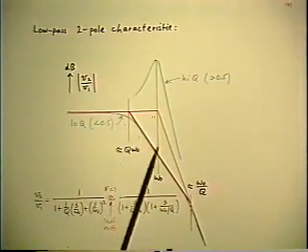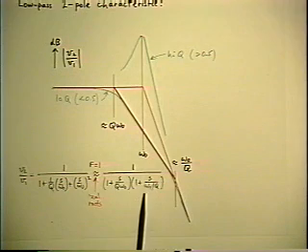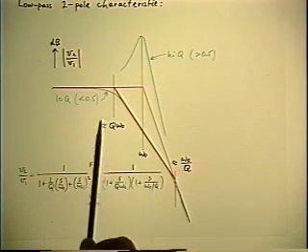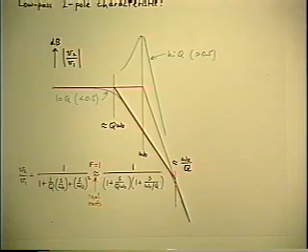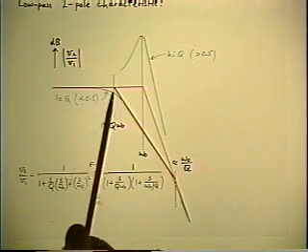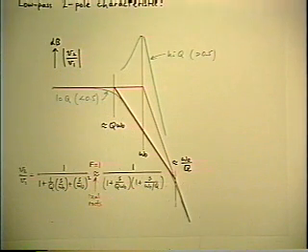On the other hand, if Q is small, use the real root approximation, factor the quadratic into the two real roots, Q omega 0 and omega 0 over Q. Again, looking ahead to the design application, which is the only thing that's important, you may want to design the quadratic so that it does have low Q's, which enables you to fix those corners where the specification requires. It tells you immediately what value of Q you have to put those corners in a certain position.